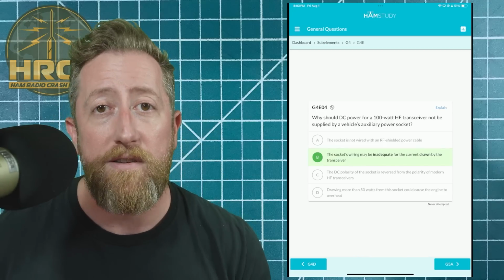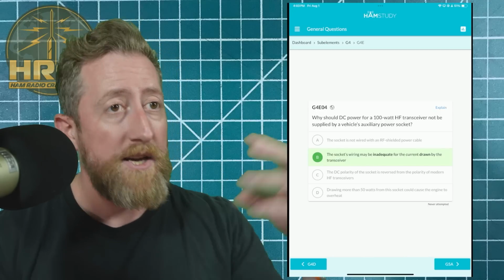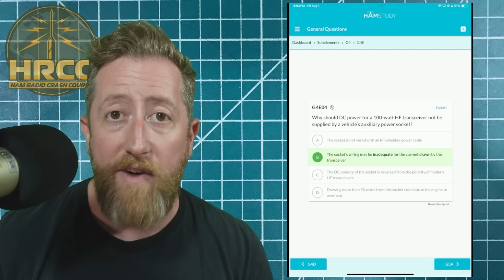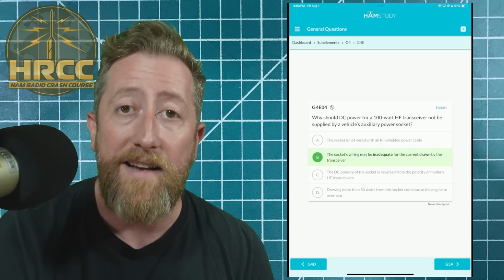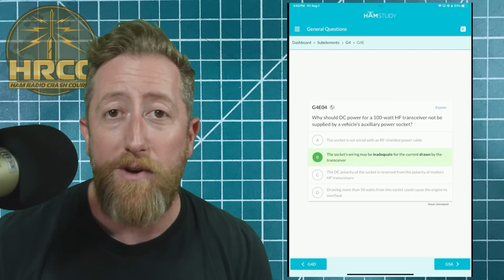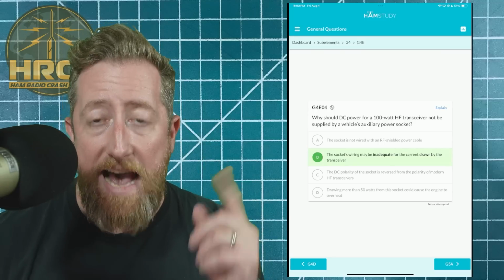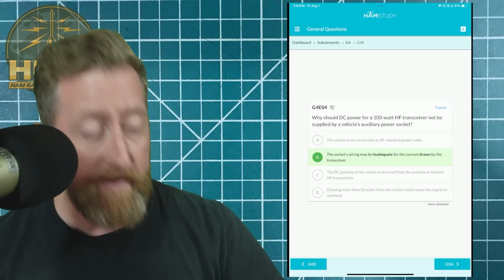You could damage the system. You could melt the shielding off of it. You could rub against something which starts it on fire. Has that happened? Absolutely. Has people completely screwed up electronics in vehicles doing this? Yes, they have. That's why we say direct to battery, safest option.